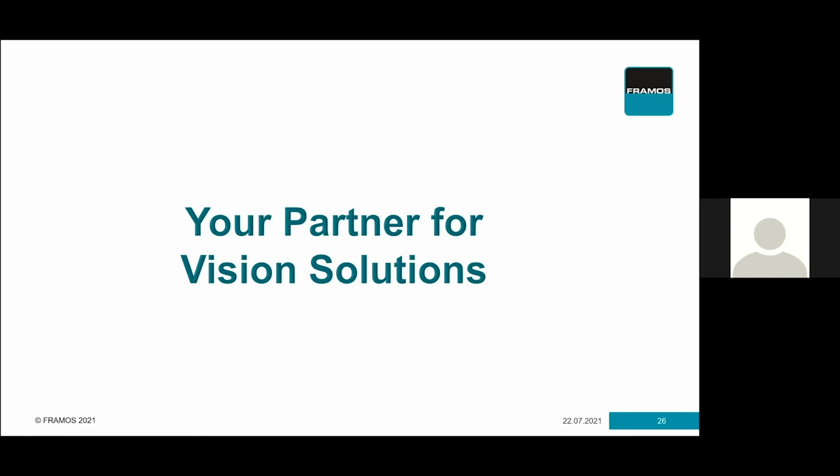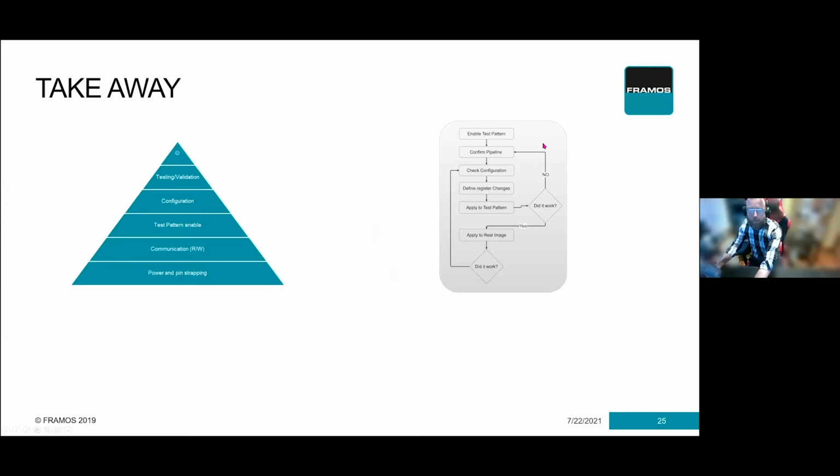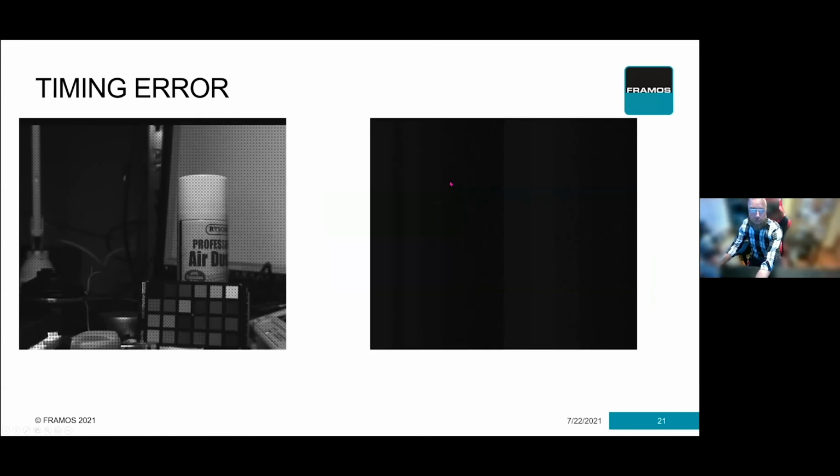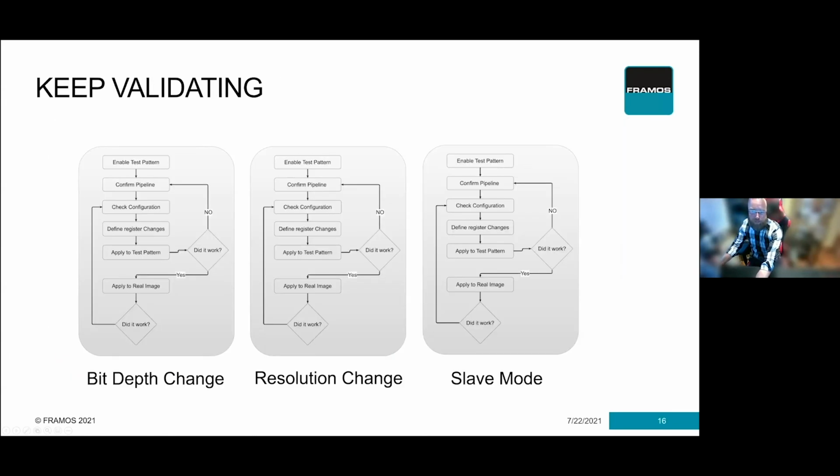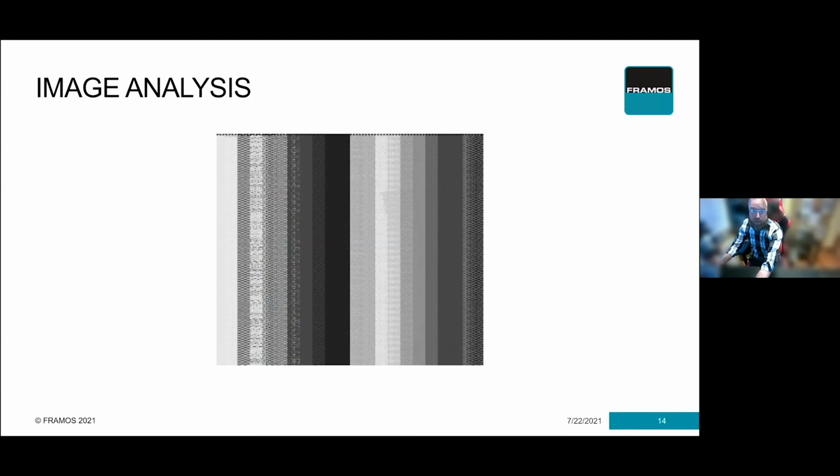So Chris, the first question I have here is: in an SLVS-EC based sensor, are there best practices to debug data streams and clocking, given that the clock is generated from the data stream? Yes, indeed, there is. We have a full path on how we go through it. If I can jump there very quickly, the slide where I presented the numerical investigation of the data within an FPGA, that was actually an SLVS-EC input.